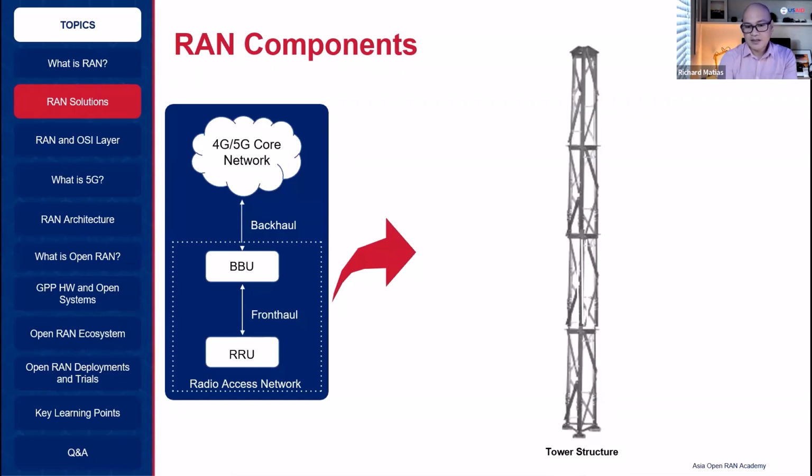Okay, so in this tower structure, we install the panel antennas, so you can see it in the typical radio access network. So you will see these vertical, rectangular antenna types. Normally it's color white or grayish white. Sometimes it measures between 0.6 to 2 meters. It depends on the frequency. So the bigger the antenna, the lower the frequency. So it's the physics of the antenna design.